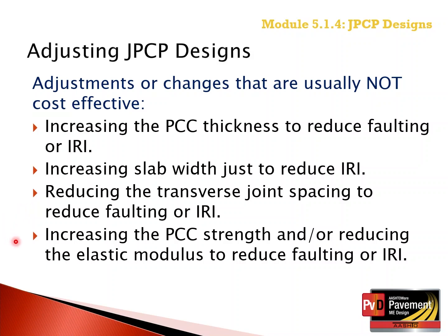Increasing the PCC strength and/or reducing the elastic modulus of the PCC slab to reduce faulting and/or IRI is usually not cost effective.